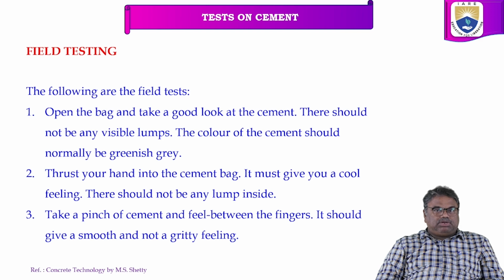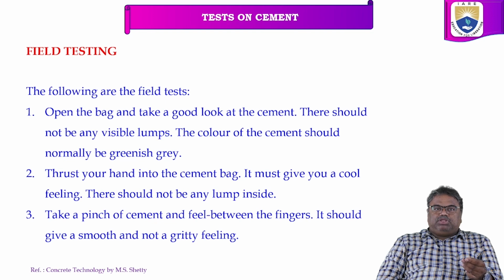Take a pinch of cement and feel between the fingers. It should be a smooth and non-gritty feeling. Since cement is a very fine material, it should have a very smooth feeling, not a gritty feeling. So this is the third test we can do on cement.